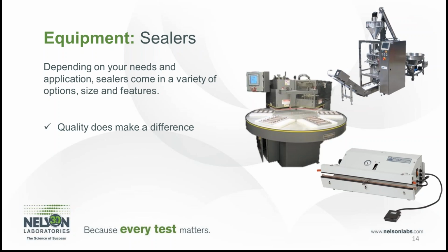The installation qualification, often referred to as IQ, looks at whether the sealer is level, whether it can be turned on, plugged into the appropriate power sources, looks at the temperature, the time, the pressure, making sure that those all are functioning properly.